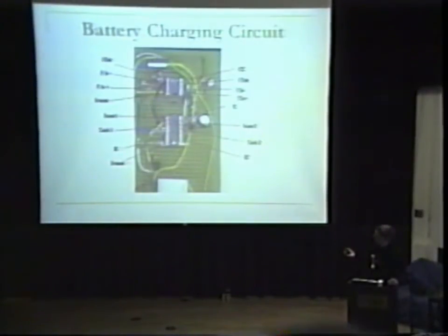And the two clocks on both sides of the chips are tied together, along with both resets on both sides. So that would engage the chip, making Q1 go high, driving the transistor and opening the relay. And then I had to get a delay in the circuit that would prevent the relay from flipping instantaneously and burning itself out.